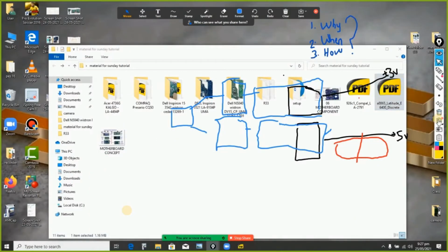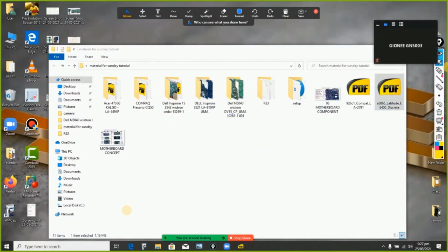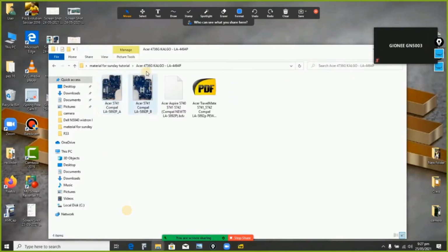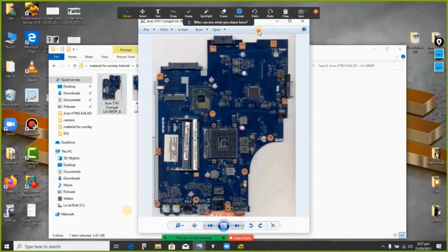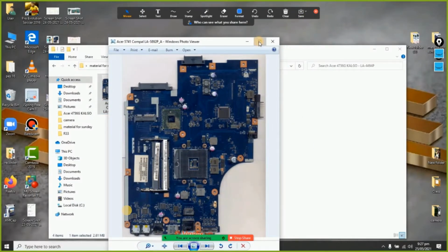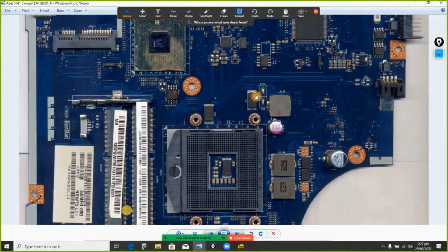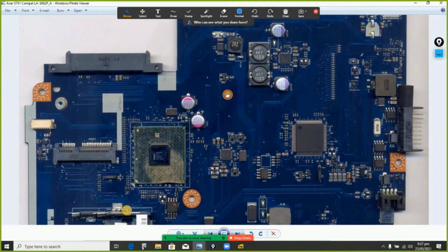Now I'll try and open a few motherboards here to explain what I've illustrated earlier. Firstly, if you are looking at a motherboard, how do you figure which part is the standby section? Normally, let me say the standby IC, we call it power IC as well. In most cases, the simplest way is if you are familiar with the different ICs they use for power on motherboards, but if you are still not familiar, there is another thing.